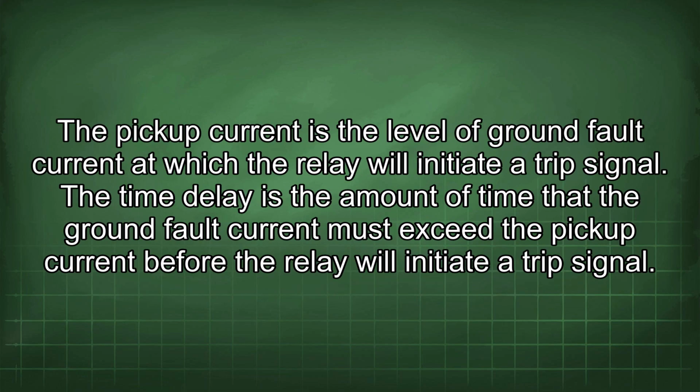The pickup current is the level of ground fault current at which the relay will initiate a trip signal. Time delay is the amount of time that the ground fault current must exceed the pickup current before the relay will initiate a trip signal.